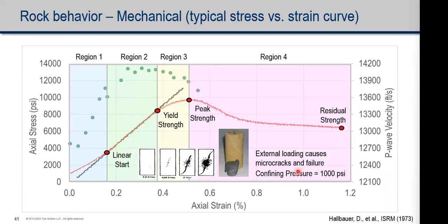Well, when I see a typical brittle stress strain curve, I show you one here in red. You're concave upwards, I call this region 1. You've got a linear region, I call that region 2. You measure an elastic limit or a yield strength, and you begin concave downwards. You reach the peak strength of the sample, and of course you're in failure at that point.